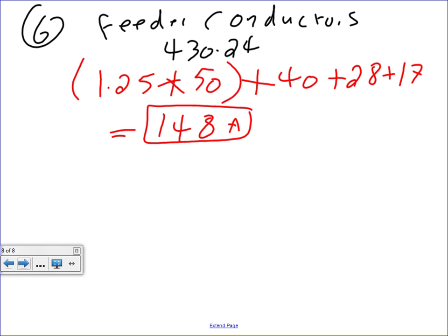I thought our full load amps was 45. From the NEC Codebook. Okay. That's a good question. You take the largest horsepower motor, take the amps of that largest horsepower motor, multiply by 1.25, add the full load current from the NEC Codebook for all the other motors. Okay, so what do you get?